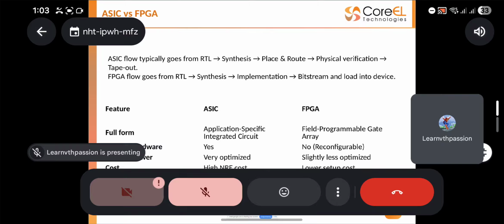Even the people who are using the Cadence tools will integrate Calibre with the Virtuoso tool for running the verification. If you browse about Calibre, you will get to know it's a very industry standard tool. Mainly, why we do the verification is, for example, you have some requirement and you will design some silicon. You will design the circuit, then build the layout for that and generate a GDSII. GDSII is nothing but a graphical design. Once the graphical design is ready, you will take it to the foundry for the tape out, for the fabrication part. But you cannot take it to the fabrication directly without verification.